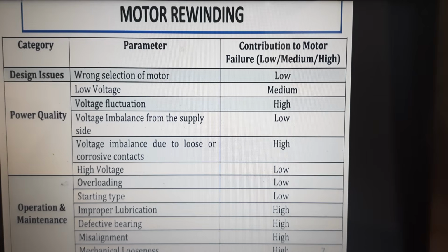So we have to take care in your routine maintenance why the motor is getting derated, either due to power quality, or due to the power inputs not being equally given to the motor, or due to the operation and maintenance on the mechanical side of the motor.